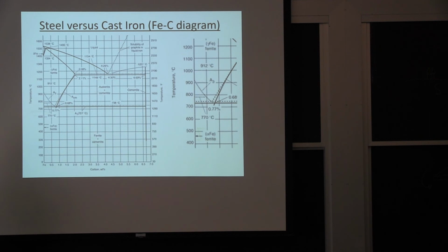Now, when I'm talking about cooling it off quickly, is you cool it off quickly enough that what you form is not in the phase diagram. And that's the martensite. And so I think you asked about a phase transformation or deformation that will cause a volume change in the material.